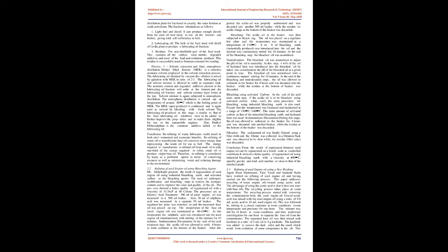Dehydration: the oil is heated to 130°C in a closed vessel to boil off emulsified water and some of the fuel diluents. The point at which oil contains the maximum amount of dissolved water is termed the saturation point. The higher the temperature, the higher the saturation point, and hence more water is held in solution, in the dissolved phase. Similarly, the older the oil, the higher the level of water that can be dissolved.